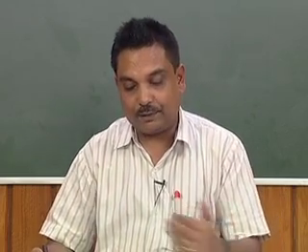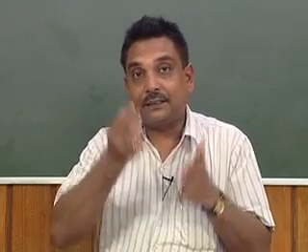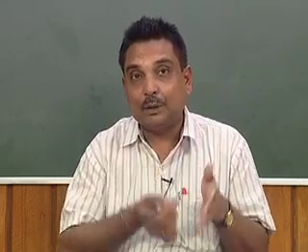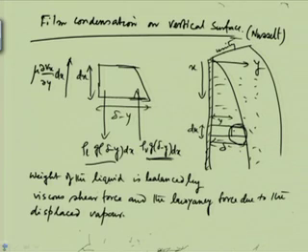Some of the assumptions we have already taken, like the flow of the condensate fluid is fully developed and laminar, and therefore we have got a velocity profile of that kind, because the viscous shear drag, mu into del u by del y, that is dVx by dy, is the Newton's law of viscosity being applied. And then the interfacial shear force between the condensate and the vapor is also taken into consideration. The meaning of this is that in this region there is no shear force.